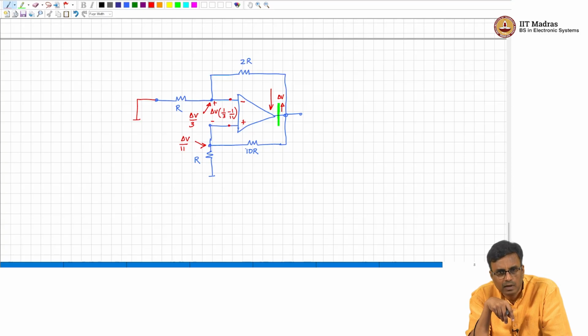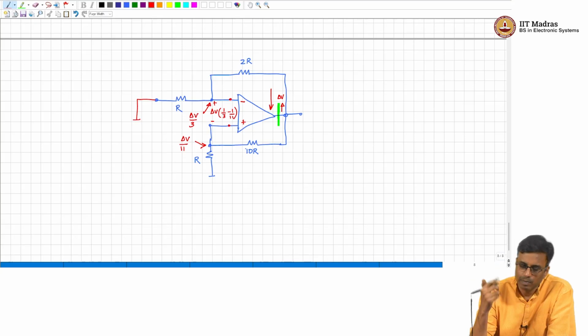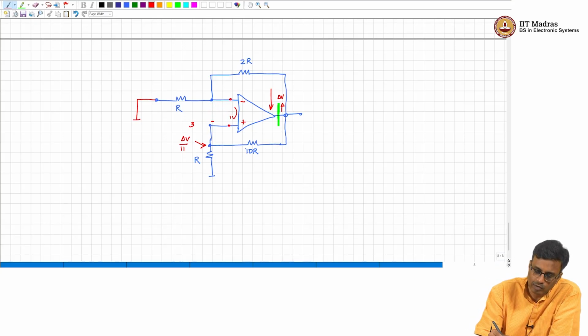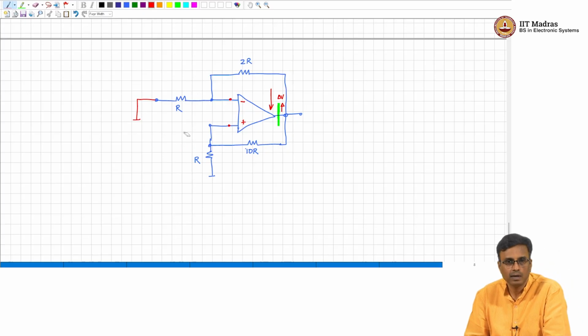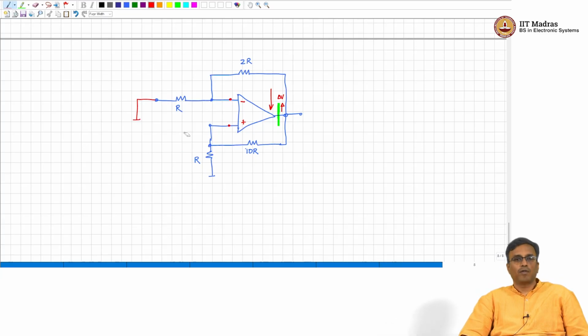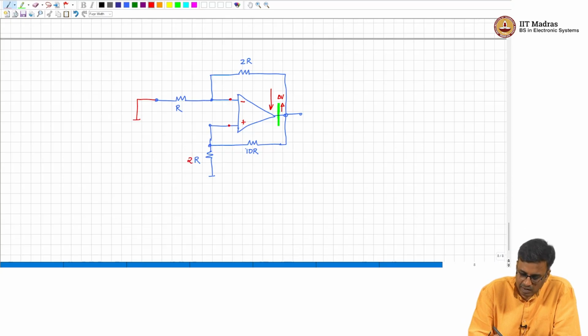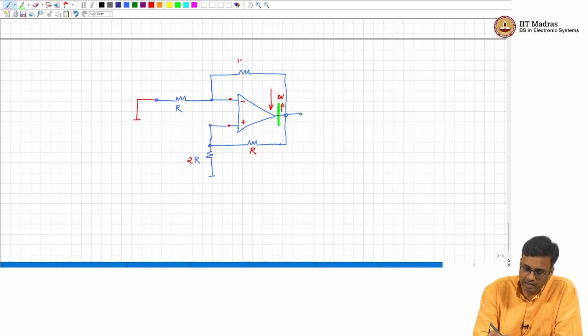become negative. So, does this choice of signs result in positive feedback or negative feedback? Results in negative feedback. So these are the signs of the op amp. Okay. Now, for some other choices of resistor values, let us say I made this 2R and this R, and if I made this R and this 10R,